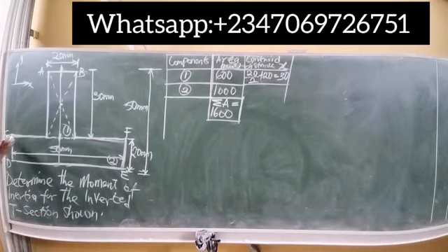Locate this center of mass for this first shape, although it's not necessary, it's not a mandatory thing, just a thing to note. Now I want to find the central distance x. So I said the width always is what? The segment x. The width for this figure is simply from C to F or from D to E. This is the width, and it's given as 15 millimeter.